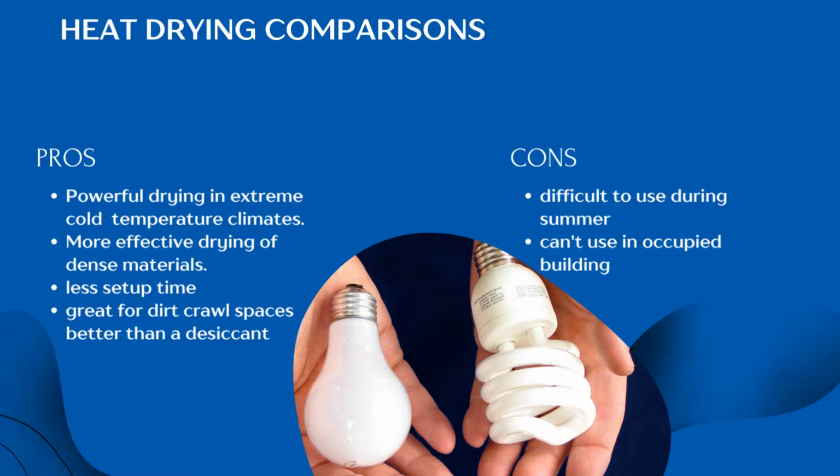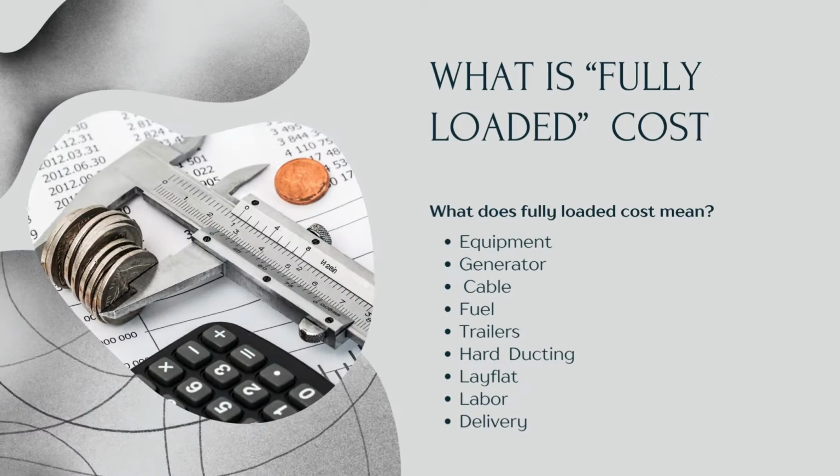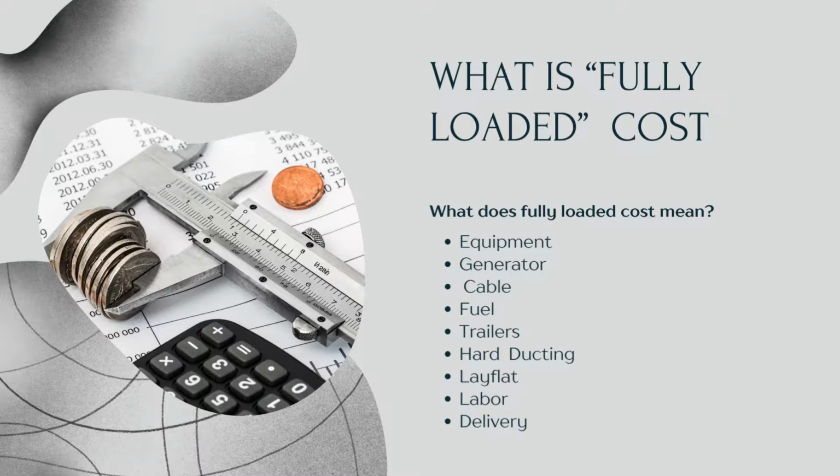We hadn't really talked about conventional LGRs, but they really have no place in the drying industry. Those are good to put in your basement and try to control a little bit of humidity if you've got damp moisture in your basement and do stuff like that, but they really have no place in the drying industry. They just simply won't get the grains low enough to be able to help you get anything dry. So hope it's been a little bit helpful today to go over some of the dehumidifications.